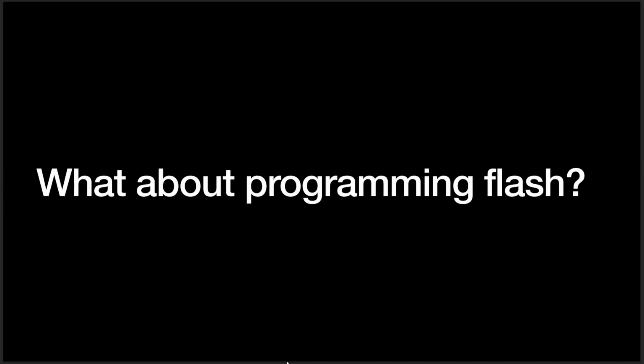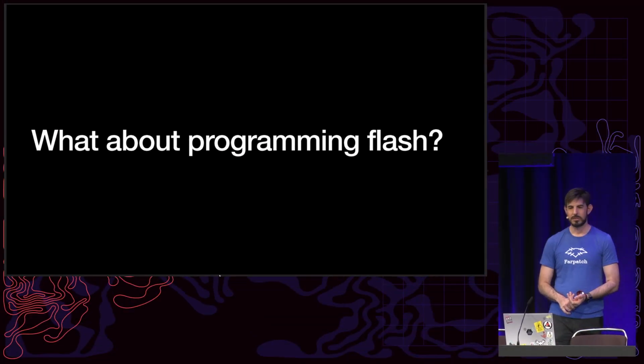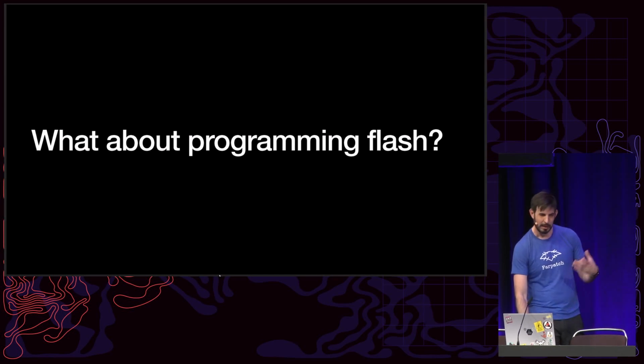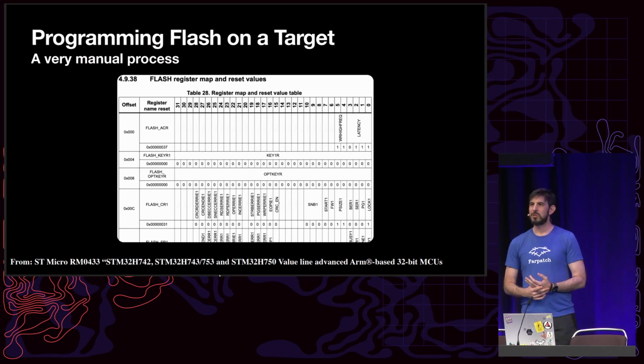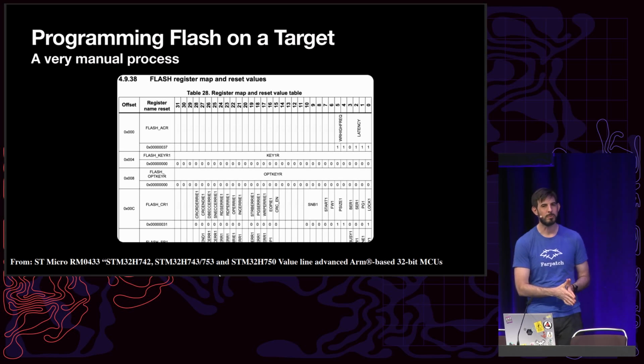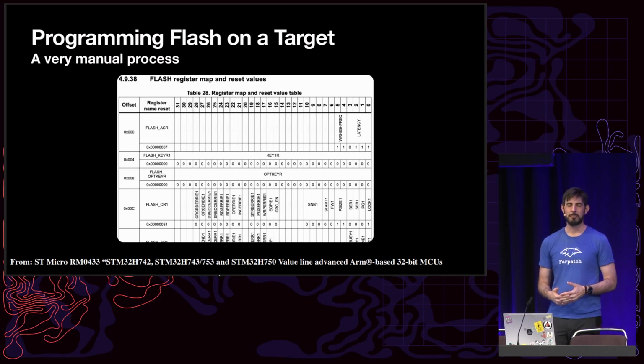So what about programming Flash? I did mention in the discussion that we talk about programming Flash. Well, that is basically writing to memory. And so what you can do is you can actually write the driver for the Flash in your debug software. And you can get pretty far with this.